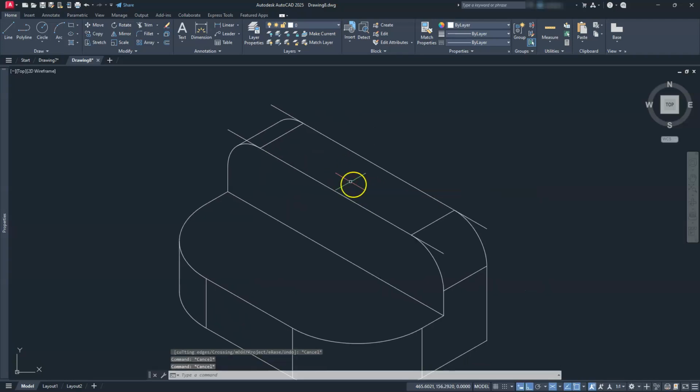Okay. Let's go ahead and put our circles in, right? Now we know that we're on this face here, and we can do some calculations and figure out that. We already know that if you watch the breakdown from the other video, from this top face going up, that circle is located at a distance of 10, right? So what I'm going to do is I'm going to create a circle here, and I'm going to go ahead and switch to the isometric. Let's see, that's F5. To my isometric left here.